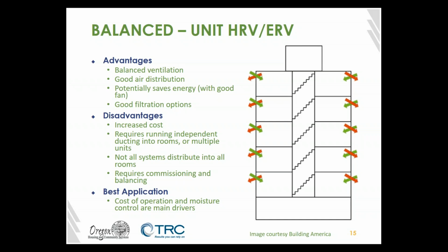So your incoming air can be filtered, can be going exactly where you want it to go, and your outgoing air can be actually leaving your apartment, leaving it where you want it to leave, and they're doing it at the same rate, so you're not pushing air in and out unit to unit, and you're not getting as much sharing across the dwelling units, across the apartments in the building.